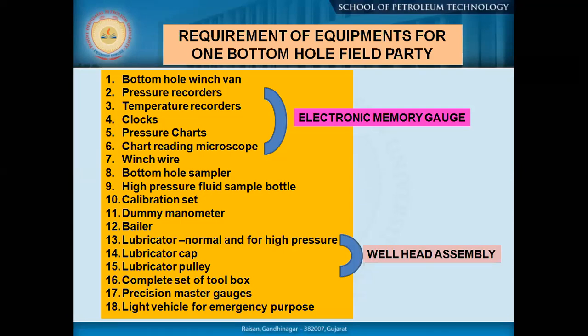Then you need to carry other instruments for your own study, because you are technical people. As a responsible engineer, you should know all the information of that specific well before going to the well site. Is it a producing well, or has a workover job been done, what is the status of the well, what is the drill depth, what is the casing shoe level, where is the perforation done, what is currently happening in the well.